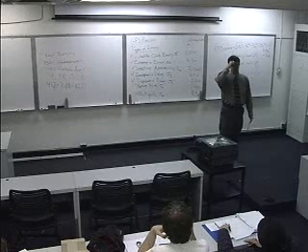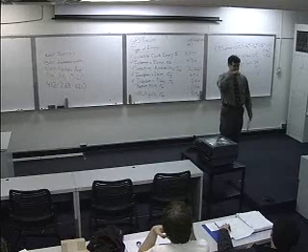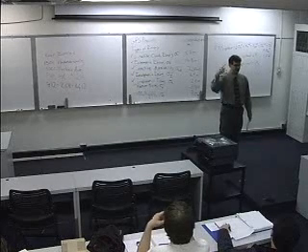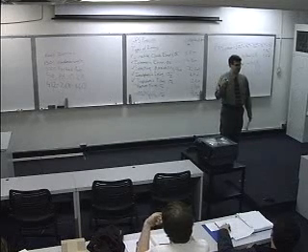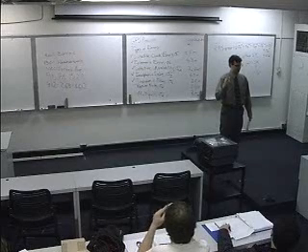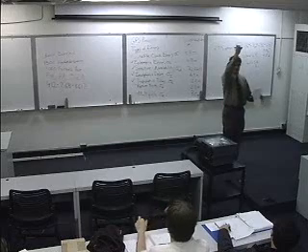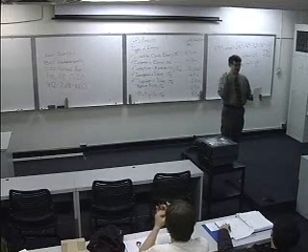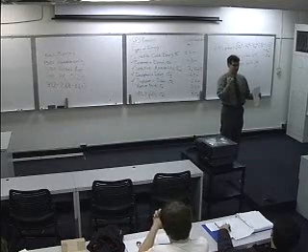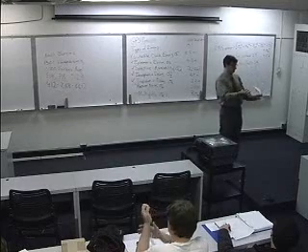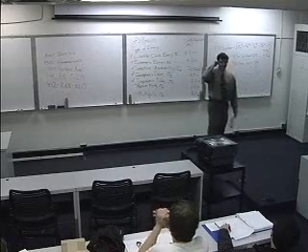Now, what you can do in the case of differential GPS is you use a fixed known location that has an active GPS receiver. And it does things like measure the ionospheric delays, because it knows precisely where it is. It can calculate what that ionospheric extra delay is. And then it broadcasts that on a separate channel. And that would be an example of how to augment the system.